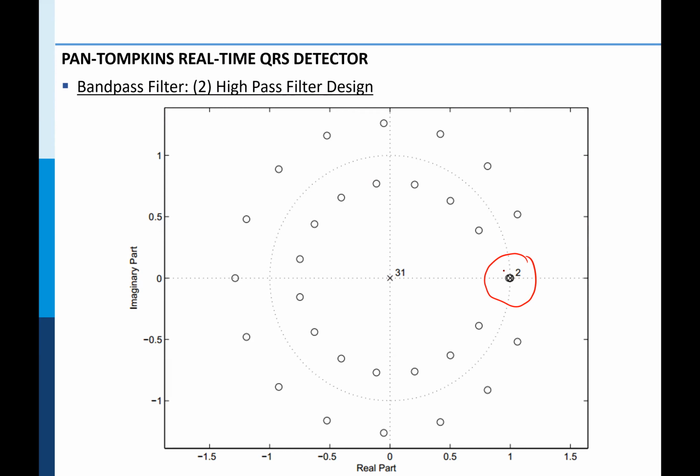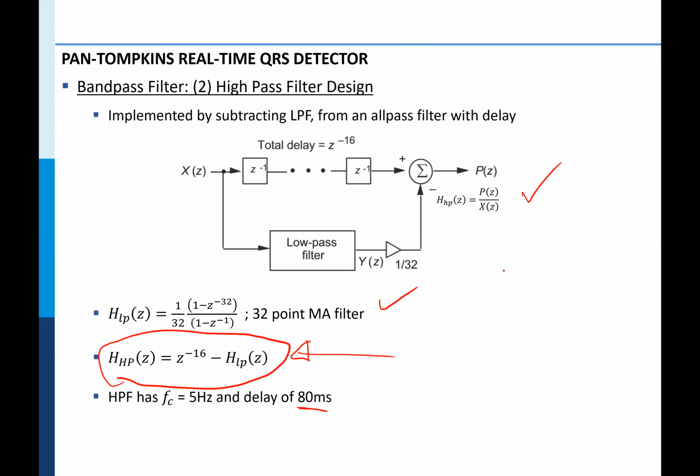So what they have done is that they have put certain poles right on the spot on the unit circle, and they're not doing anything to the stability. All it's doing is a mathematical convenience where the zeros are getting cancelled. Okay, so the zeros and the poles cancel each other, so it doesn't have any impact on the stability of the filter. Okay, so again, this is a very neat design. The reason they have to come up with this kind of a configuration is to essentially make sure the filter coefficients that we just saw before are all integer values.